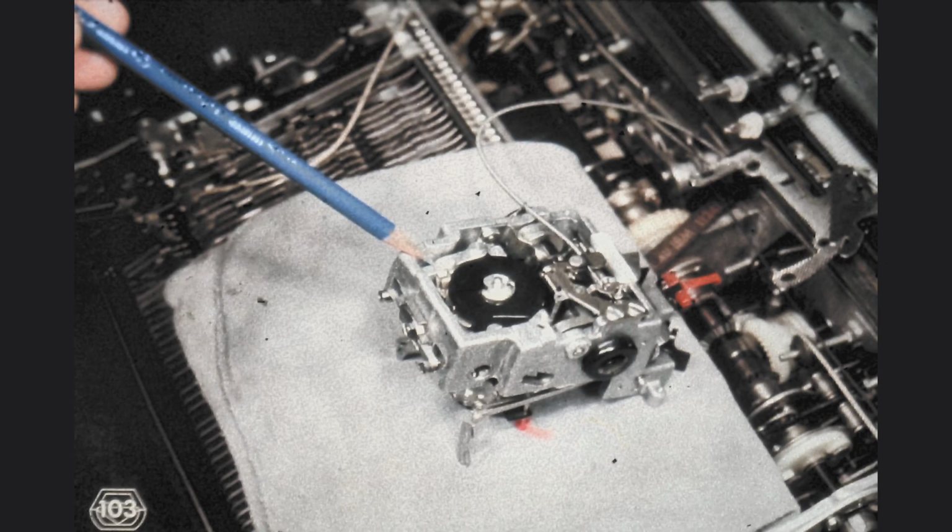With a rag placed over the keyboard, we can easily set the carrier upside down on top of that rag and work on it without even having to remove the velocity control cable from the carrier. Try not to twist the velocity control cable unnecessarily. One of the reasons we wanted you to take the carrier out like this was to investigate the purpose and construction of this rotate tape guide. Remove it now by extracting the 2 screws which hold it in position.